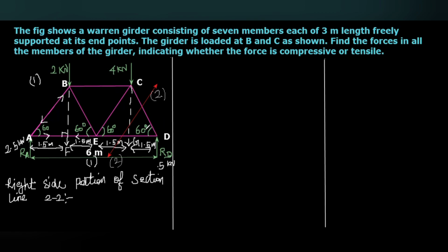Here, first I just draw the free body diagram of this. Here you can see there is one inclined force in the member, and one horizontal force in the member. There is a vertical upward force RD. This is point D. This is the force in the member TCD. This is the force in the member TDE, or otherwise ED, whatever.